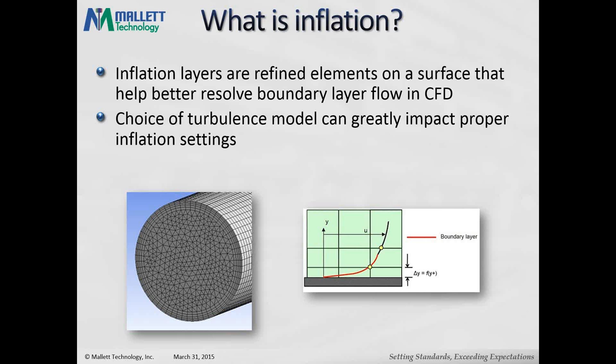So particularly with highly turbulent flows where you might have large velocity gradients near the boundary, near the walls of your pipe or what have you, you'll want to use an inflation layer to more accurately resolve that velocity gradient and pressure gradient, which is shown in a cartoon there on the right-hand side.